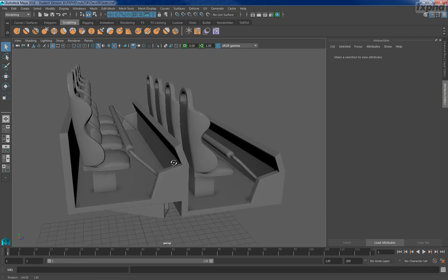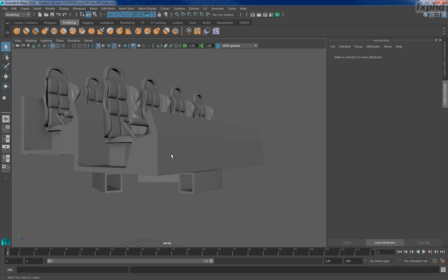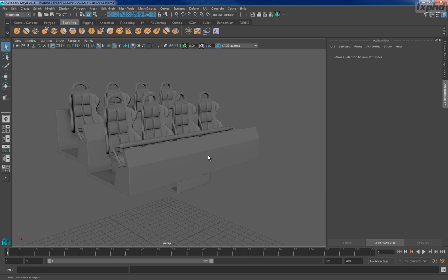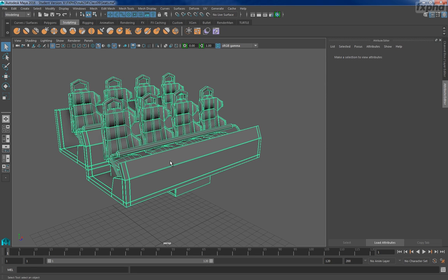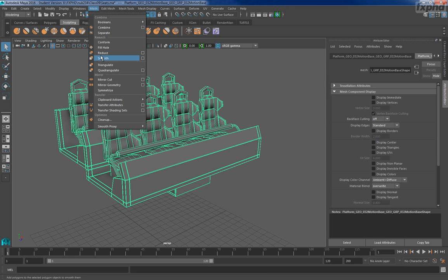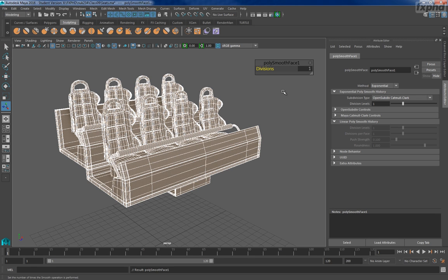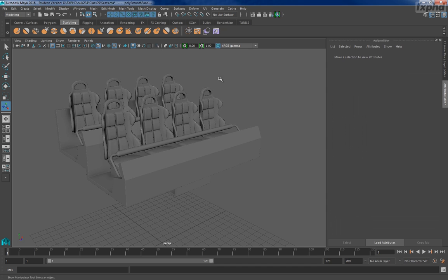And this is our new version of the top of the base. The base, the ride platform, first of all, it's in sub-D mode, and we can't really see sub-Ds in Nuke yet. So you have to set that to subdivision 1, and then we have to set this to smooth mesh. I usually leave it at 1 subdivision because it's pretty heavy as it is, but that gives us a good resemblance of what we need with good interactivity and speed.